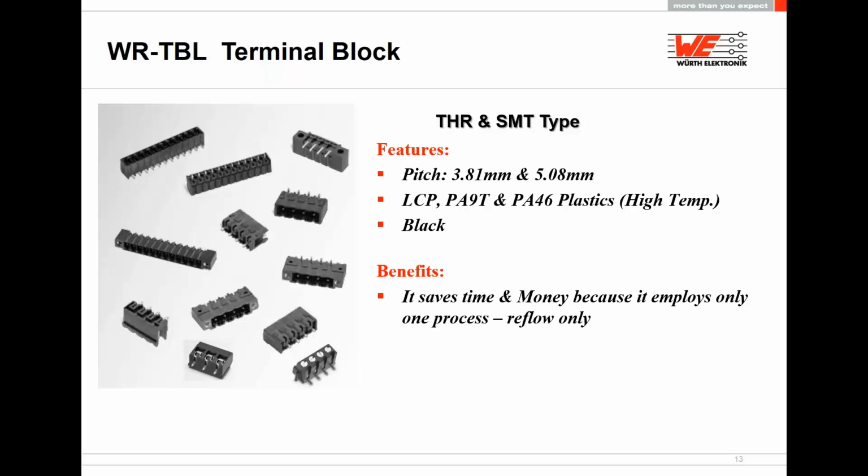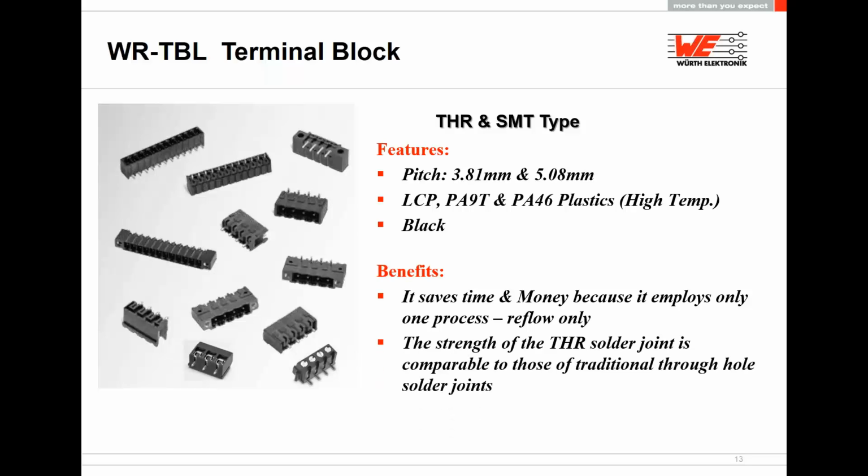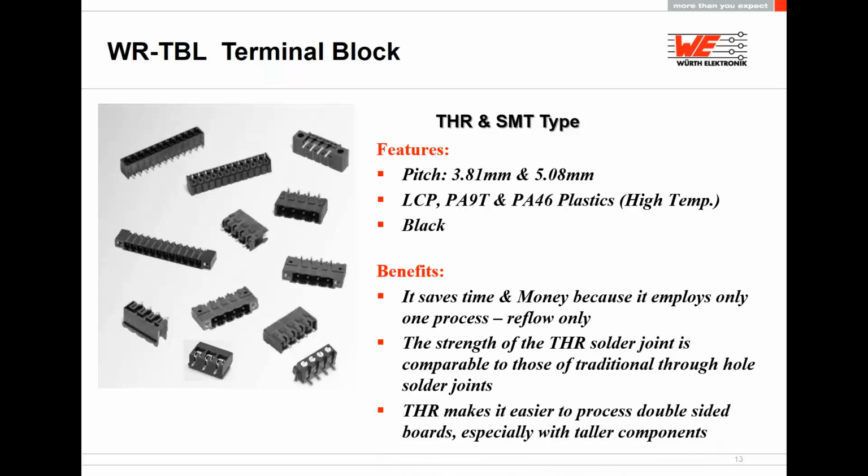Benefits of the through hole reflow. It saves you time and money because it employs only one process, which is a reflow. The strength of the reflow solder joint is comparable to those of traditional through hole solder joints. Through hole reflow makes it easier to process double-sided boards, especially with taller components.